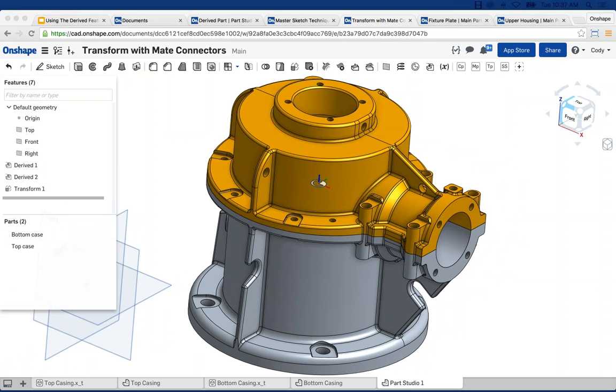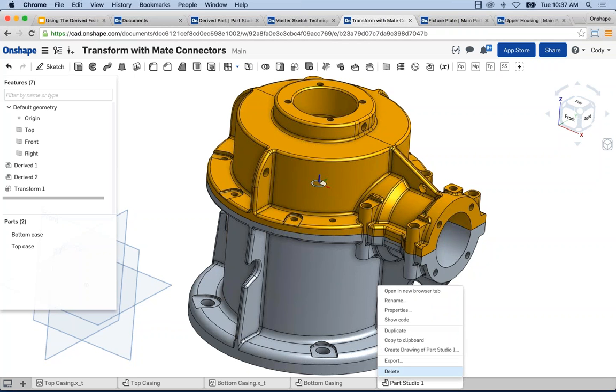Question. Is it possible to copy a sketch or object with edit capabilities without the parent-child relationship? You can copy a part and paste it. You can duplicate a part, you can copy and paste a part, and in that case, it does not have any relationship whatsoever to the original. So I could right-click a part and say copy to clipboard and paste it, and then there's no relationship whatsoever between those. You might call it a dumb copy, so to speak. It's not derived, so it doesn't update. So that's something I might try if I did not want them to update.